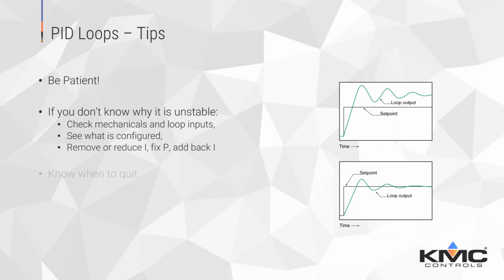So just to review the highlights, or the major tips, that we would give you to tune those control loops. First one, again, be patient. Especially as we get started, I'm looking at my live trend or my table view, and I put that first P term in there.